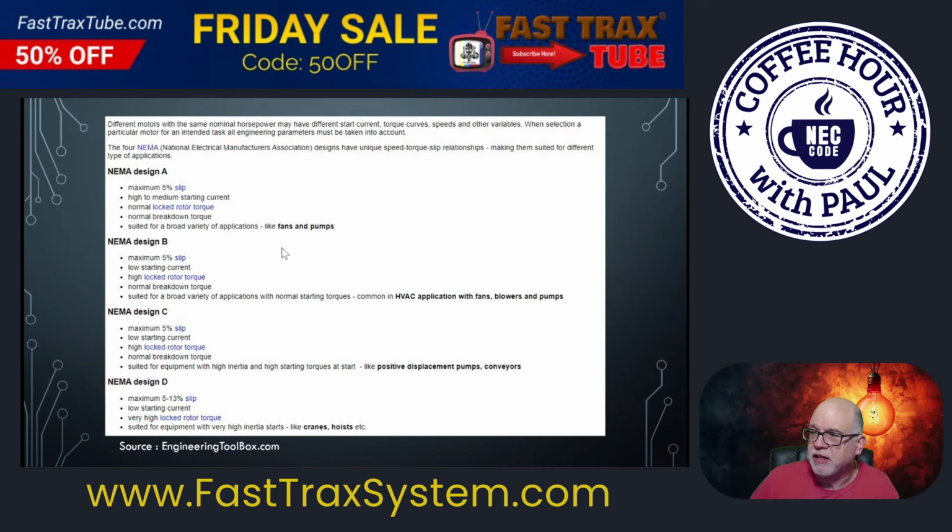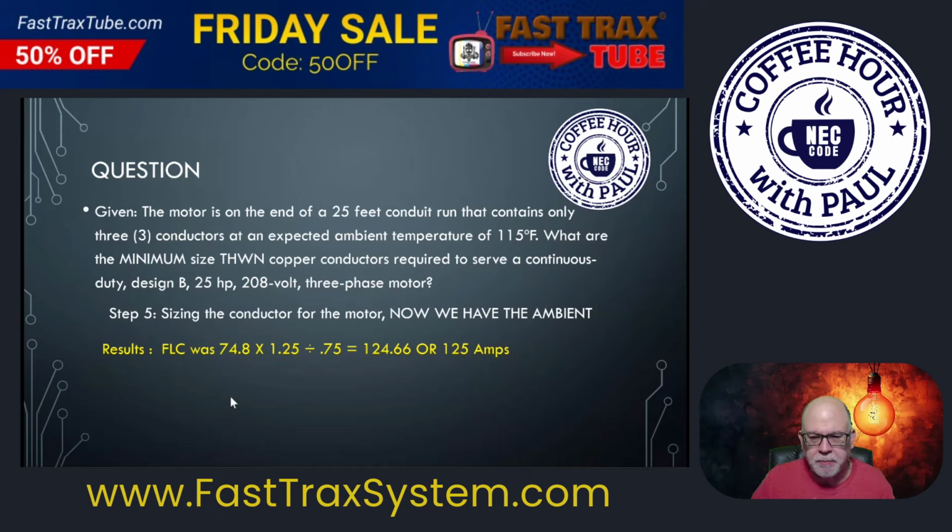All right, back to our question. Now that we have the ambient, we're going to work this the way it's supposed to be worked. That FLC is 74.8 amps. We're going to multiply that by 125% because that's our starting value. We can't be less than that. Then we use division to go up and look for a conductor. Once we have the final number, we can use multiplication to check our work, but we use division to work our way up.